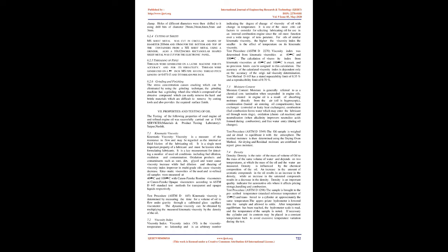6.2.5 Threading of pipes. Threads were generated on a lathe machine for its accuracy and for its versatility. Threads were generated on an inch MS pipe having thread pitch length of 0.07143 and 14 threads per inch.